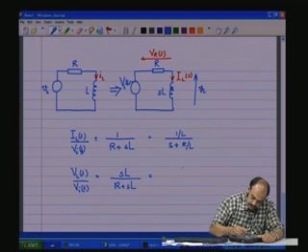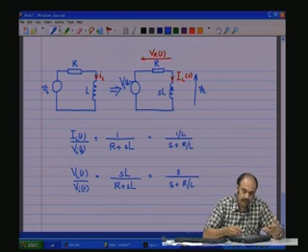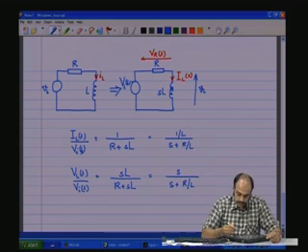This is equal to S divided by S plus R by L. You see, this is 1 by time constant, just similar to the capacitor circuit 1 by RC, 1 by time constant there also. You have a 0 in the numerator, S is equal to 0, and one pole in the denominator at minus R by L. These two are similar in terms of the poles, but in terms of the zeros they are different. This is decaying in nature, this is not decaying in nature. This will settle down at some value which is whatever the input value would be.